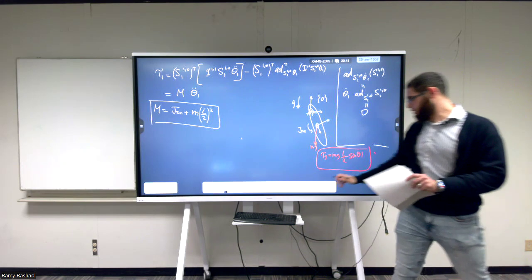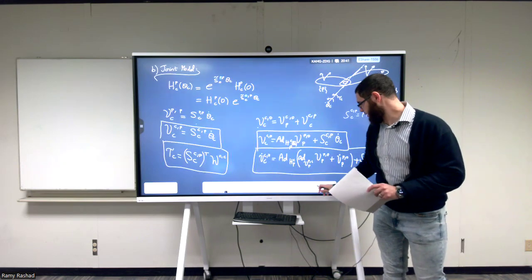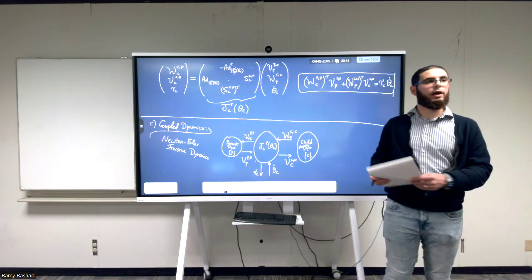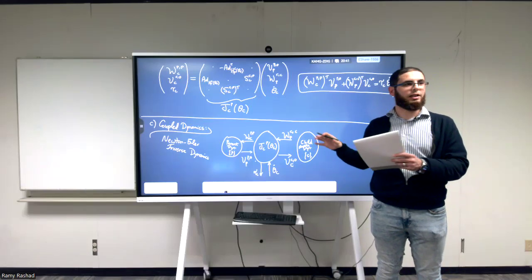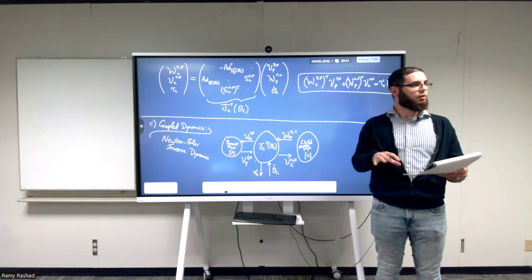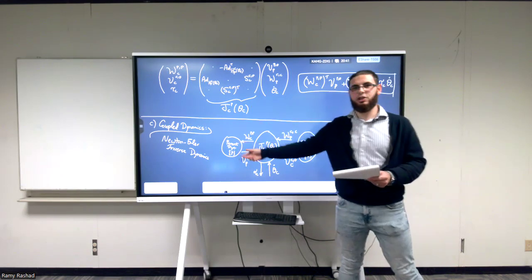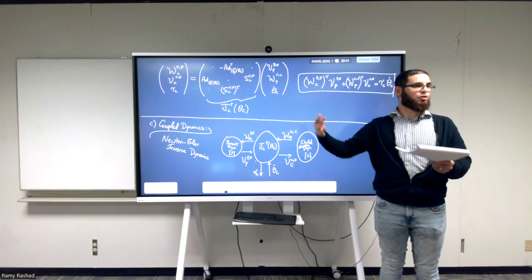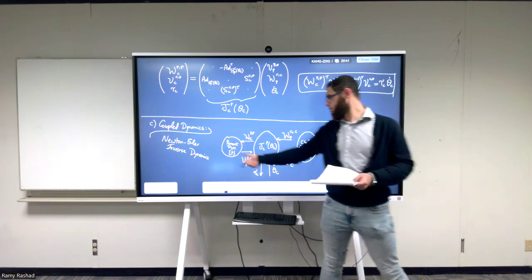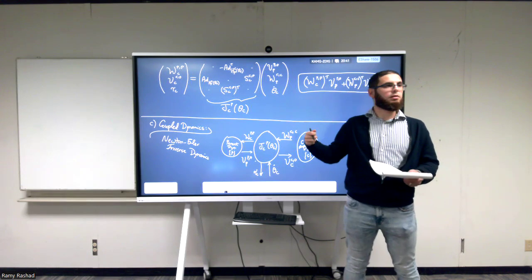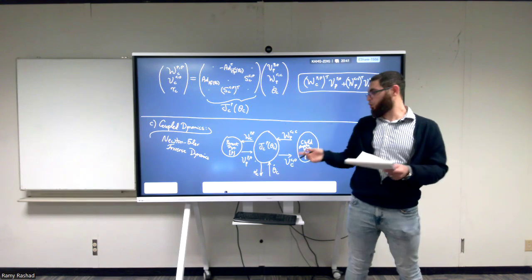So now, let's recap very quickly. This is a very fancy way to derive the pendulum dynamics. Of course, we're not doing this to derive the pendulum dynamics. This is just showing you that this is a very general way to derive the dynamics once you reduce it. What I wrote here is the Newton-Euler inverse dynamics, and you need to reduce it down depending on the constraints.